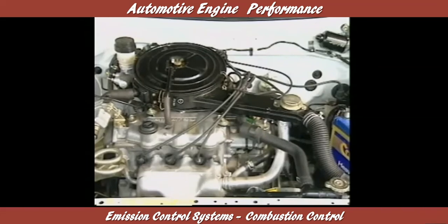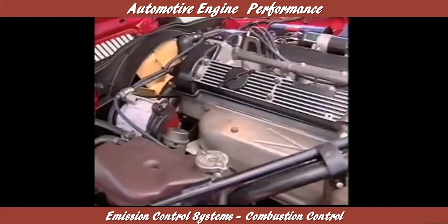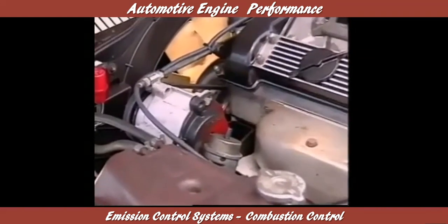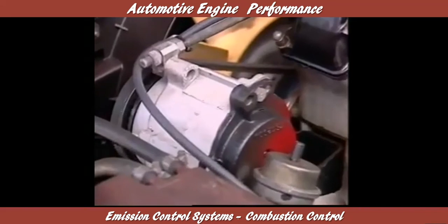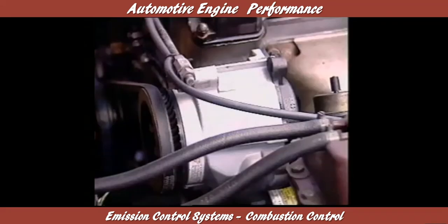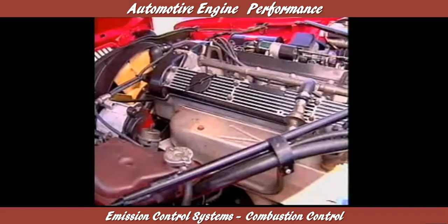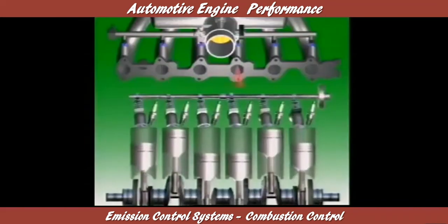This method suits engines with 4 cylinders or less because their exhaust pulsations are further apart. Larger capacity engines may use an air pump to supply a larger volume of air. The pump is normally driven by a V-belt from the engine crankshaft and forces air into the exhaust ports. Some of the engine's output is used in driving the pump.